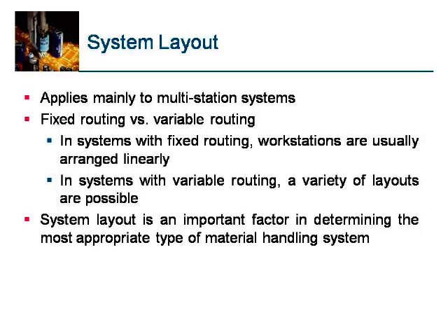This applies mainly to multi-station systems: fixed routing versus variable routing. In systems with fixed routing, workstations are usually arranged linearly. In systems with variable routings, a variety of layouts are possible, as we have seen in the previous figure. System layout is an important factor in determining the most appropriate type of material handling system.